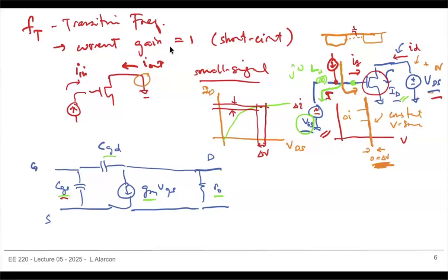To be able to get a larger range of frequencies, I want to increase that L. Ideally, I want that impedance, j omega L, to be infinite at any frequency greater than 0. That just means I can increase this so that at the frequency that I want, that pretty much looks like an open circuit. So all your small signal goes into that transistor. I hope that's sort of clear. That's the reason why we had that particular circuit. But that's one way of doing that.